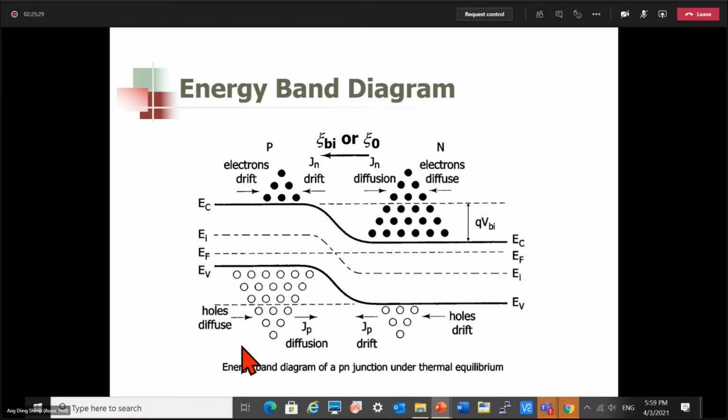Okay, so that's how you can interpret an energy band diagram. You can treat it as an inverted potential diagram, where a very positive potential exists downwards and not upwards. It exists downwards. Okay. Now, based on this understanding, we can therefore say that due to the alignment of the Fermi level, there is an offset in the band diagram between the N and the P side.